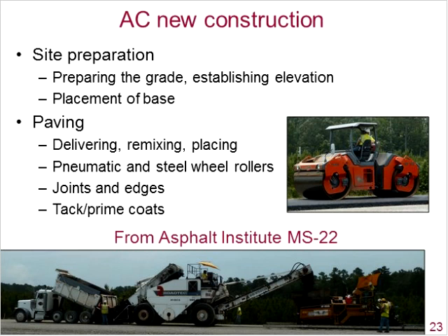And as you're building these layers of asphalt concrete, recall that they're each about 2 to 4 inches thick. You may need to put several layers down. Often you'll have these tack and prime coats in order to adhere those layers together.